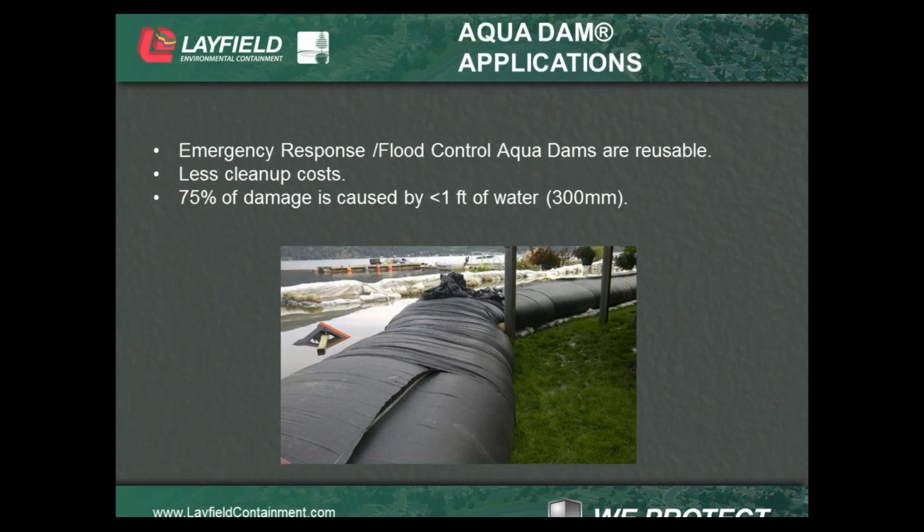So in a flood control or emergency response application, aqua dams are reusable. They can be cleaned off, cleaned out, and then stored away out of the UV. You can reutilize them several times over several years. I've seen them get put away and then be reutilized again 8 years down the road. So they are definitely storable and reusable, especially when we talk about emergency response and flood control. There are definitely less cleanup costs associated with aqua dams than with sandbags or some kind of sand or dirt berm that you might construct to prevent flooding from occurring.